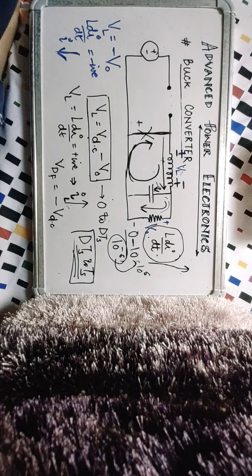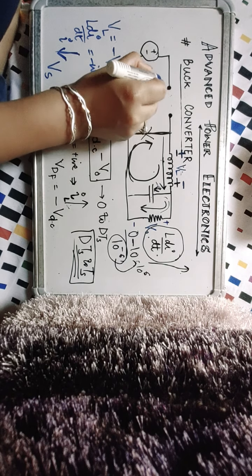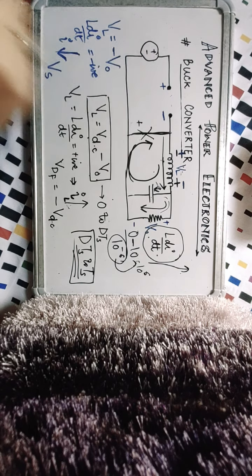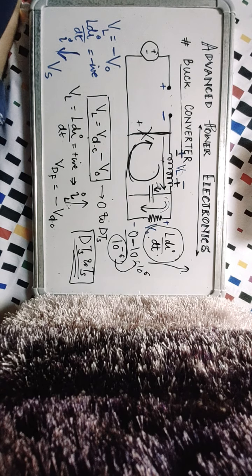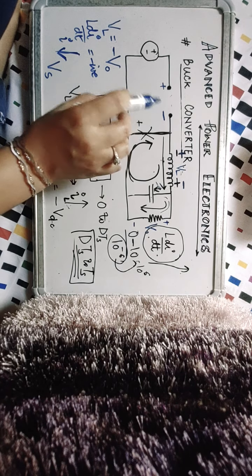Before we do the volt second balance, I want to also discuss the switch rating. What is the voltage across the switch over here? When the switch is conducting, in the previous half cycle energy storing interval, there was obviously no voltage across the switch, maybe 2 or 3 volts, but let's just neglect it when we're talking in hundreds of volts. But when the device is off, the switch is supposed to block some voltage.